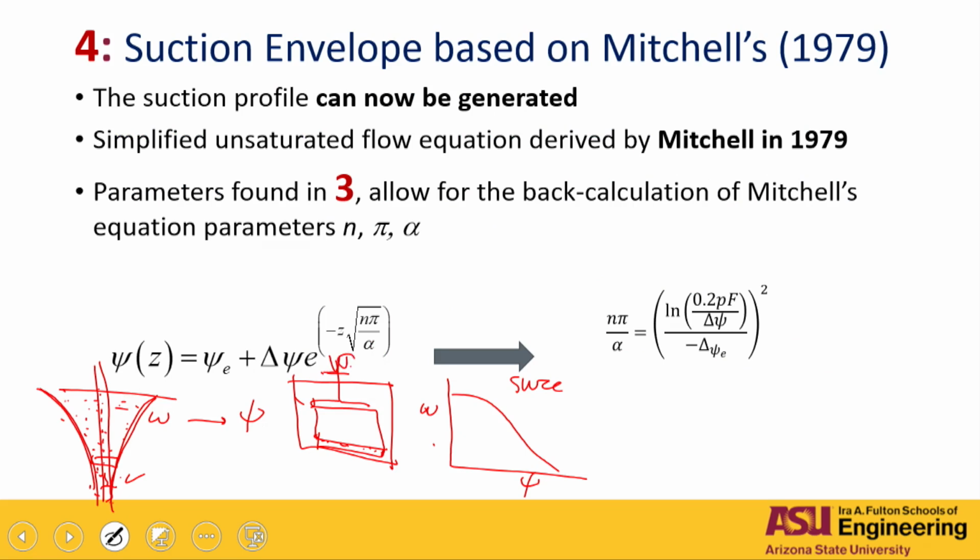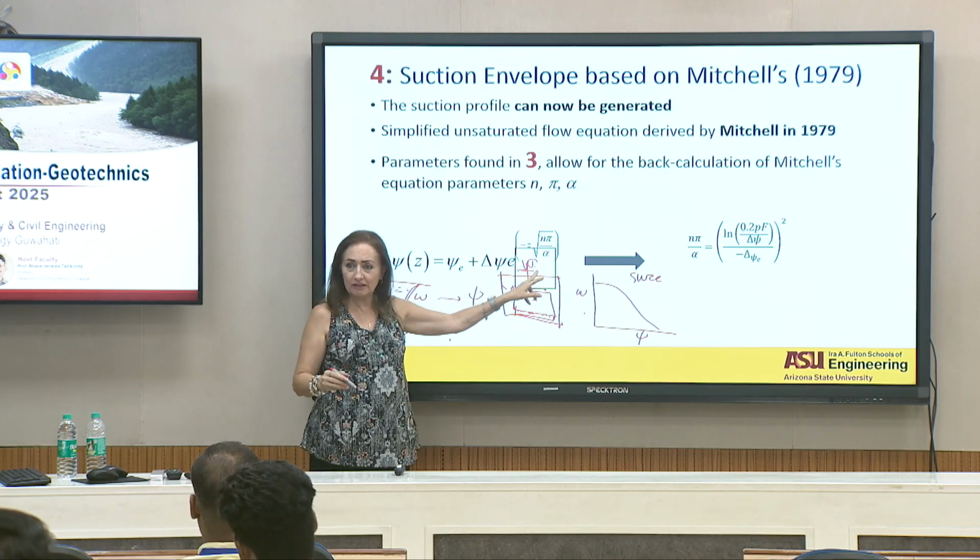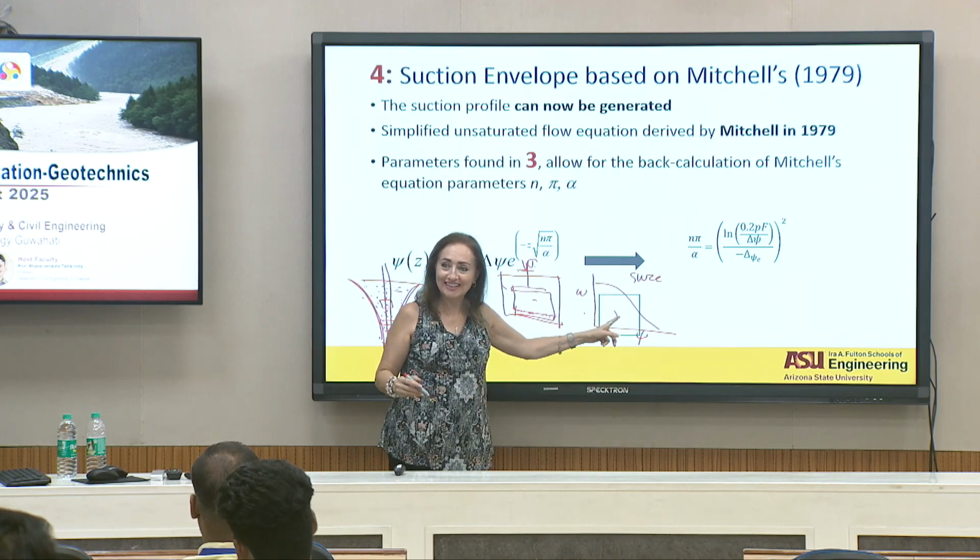You load it to that overburden pressure, and you eliminate any expansivity that you get due to the unloading you had to do. So you load it again to this point, and then after that, you do the equilibrium analysis. Number of SWCC, different overburden? Yeah, you took a sample in here, then a sample in here. You vary the normal stress. Number of SWCC? No, it's one. It's one, but corrected for volume change.